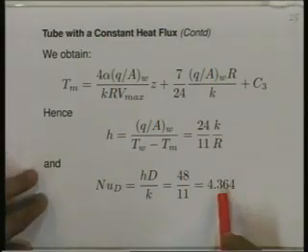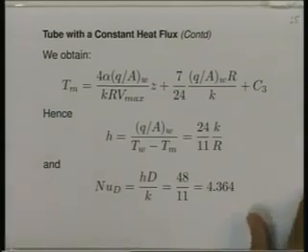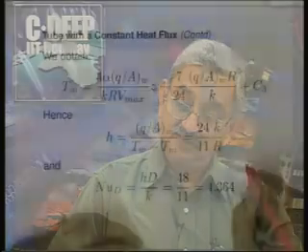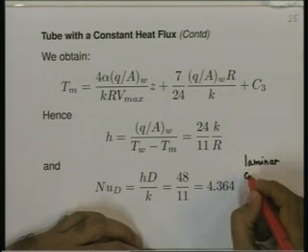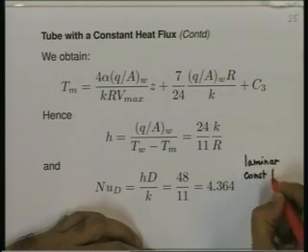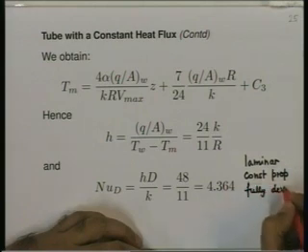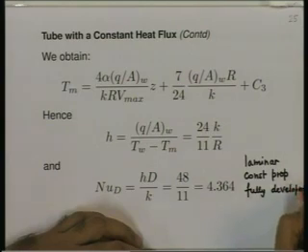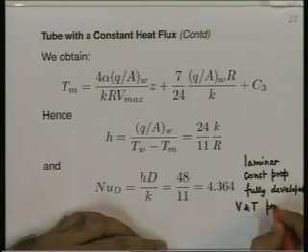Whenever you remember this, you should also remember the conditions under which it is valid. The conditions for this are laminar flow, constant properties, and fully developed V and T profiles.